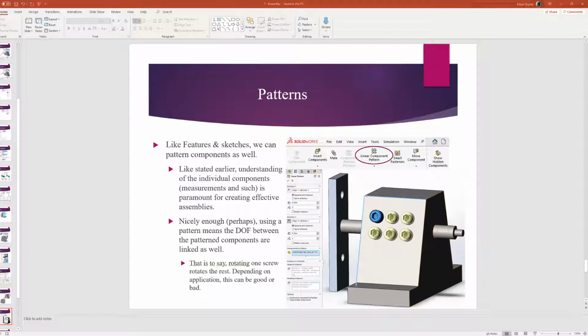So what I would probably do is something like this. There's tons of different ways that you can do this, but the first thing that came to mind is that this plate lies exactly along the plane of reflection that I want. First things first, what is this distance? I'm going to control left click on both of those, and it tells me in my bottom right hand corner that the normal distance between those two surfaces is 1 inch. Okay, cool. I'm going to use that to my advantage.